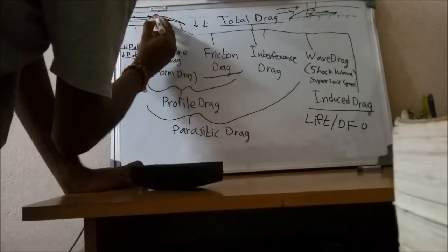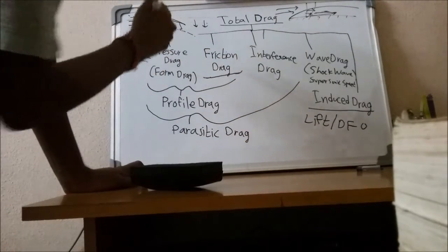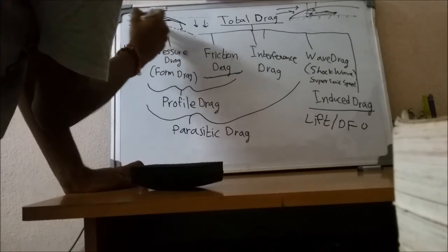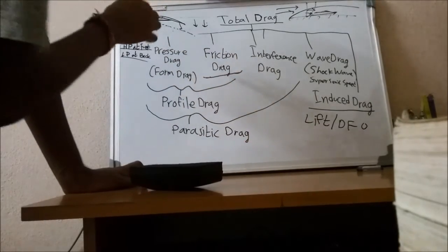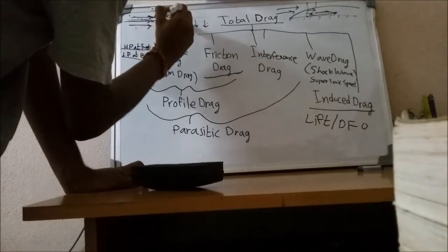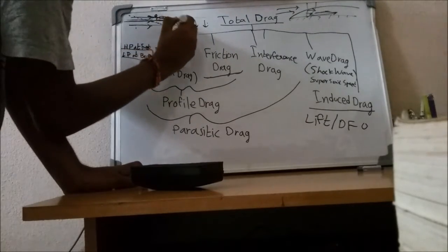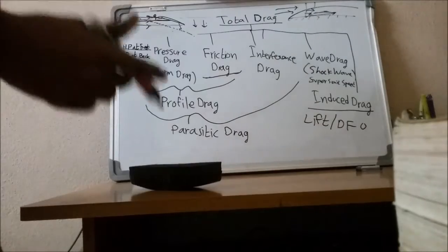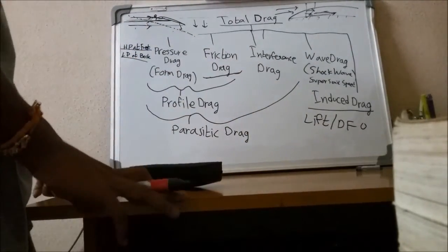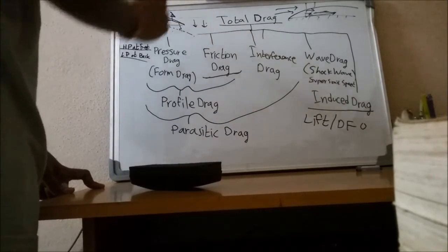So this theta that is actually happening in the real flow will be lesser than the designed theta value. The real angle of attack of the wing will be lesser than the designed angle of attack. So now the wing is looking as if it is 20 or 25 degrees, but in reality it will be only 10 degrees. So this is reducing the lift of this wing. It will reduce the resultant lift force acting on this wing.